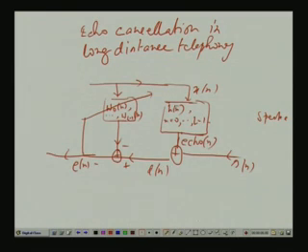If the misadjustment is very small, what will happen? They will actually converge to h(n), but with a very small difference. In that case, the two outputs will be the same. If it generates echo(n), it also will generate echo(n), because the input is the same for both.